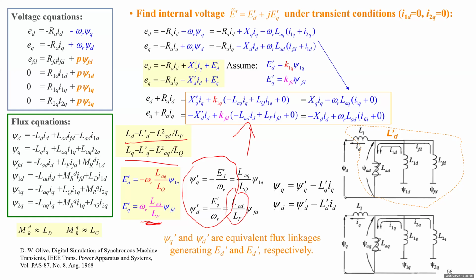So for this case, if you focus on transient stability study, you can do system generator simulation, but you only care about the time frame from maybe 1 second to 5 seconds. That falls into the transient dynamic time frame. You ignore faster dynamics. Whatever happens in the first 1 second is not important, and after 5 seconds is also not important.